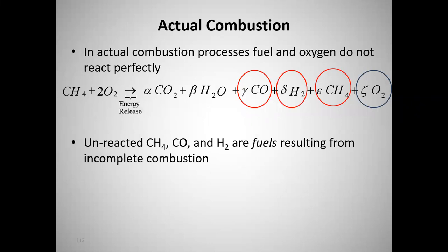Actual combustion is not quite so nice. So we still have our methane, we still have our 2 O2s, but we get some CO2 and some H2O. Now, what's this CO doing over here? That's not good. I don't want it. What? An H2? You mean some of my fuel didn't burn? A methane molecule couldn't find any oxygen. And I got some spare oxygen that was over on the other side. It was too far away, and that H2 and that methane molecule just couldn't combust. So they're going up the stack hot. So, unreacted methane.